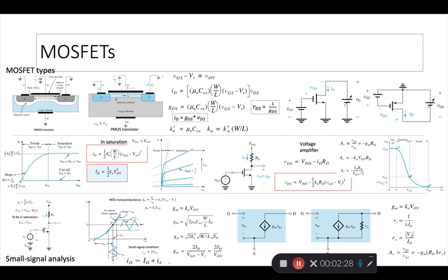Once you apply a voltage, you start to create a channel, right? And that is that induced N-type channel. It's created through depletion, and that's why you have this depletion region also shown here. Then if you apply another voltage in a perpendicular direction to this gate to body voltage, that begins the flow of electrons, right? So that is the basic idea behind the MOSFET.